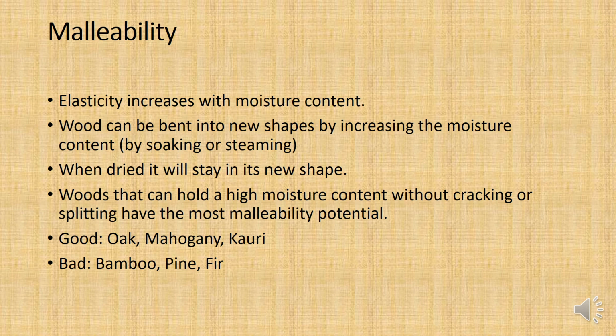And we can do that by soaking it in water, or more likely we put it under high pressured steam, and the steam can actually get into the wood faster than if you just soak it. And then once it's got a high moisture content, you can bend it into a new shape. And then when it's in the new shape, you would dry it.